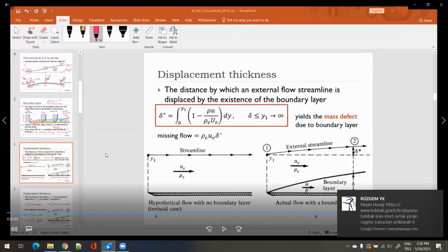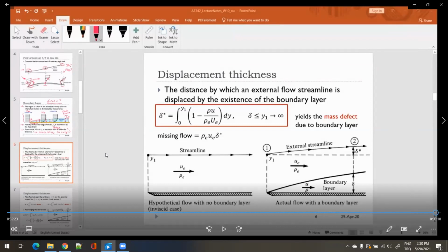Because we need that information so that we can calculate the value of delta at each streamwise location. And finally, like I explained in the video, why would we be interested in calculating delta? Because, by proper integration, we will see that later, we can calculate how much momentum loss happened in the fluid, in the airflow. And that momentum loss comes back to you as drag force acting on this solid object.